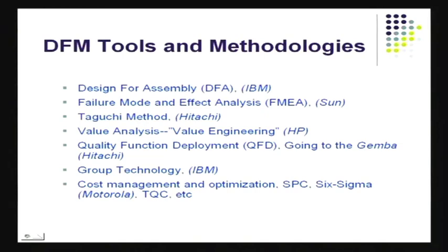Whatever the customer is looking for, I've got to capture that by capturing the voice of the customer through this QFD process. Then of course, if there are similar parts to be made, I've got to take advantage of something called group technology. If there are a lot of turning operations of different dimensions, we'll have to keep in mind that these turnings are grouped together and done at one workstation. Otherwise, you'll have dissimilar processes all being thrown at the workstation, and there will be a lot of switchovers, a lot of changes, a lot of additional setup costs incurred. This is something you'd like to minimize, and this is why you'd like to go into group technology.